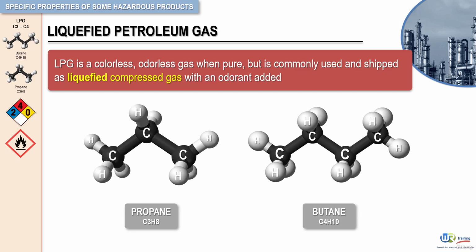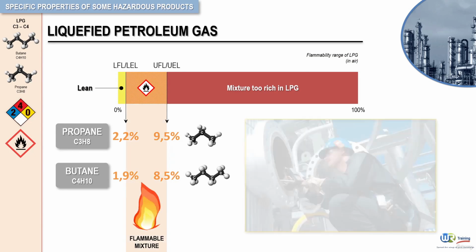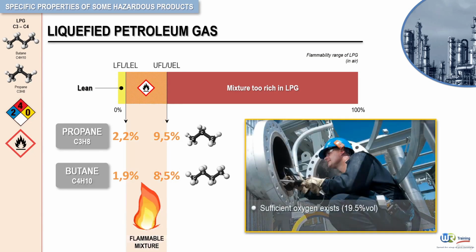In addition, liquefied petroleum gas is a flammable gas and a dangerous fire hazard. You can see here the corresponding explosive limits. Before entering a confined space where liquefied petroleum gas is present, check to make sure that sufficient oxygen exists and that an explosive concentration does not exist.